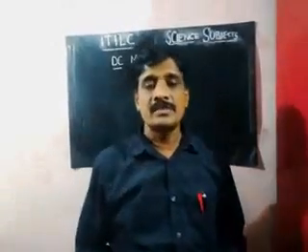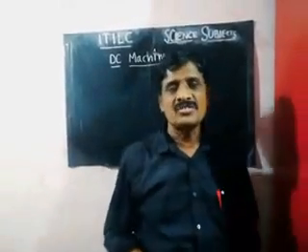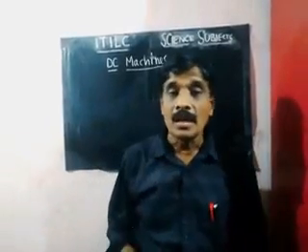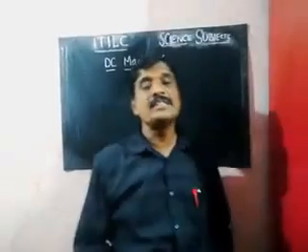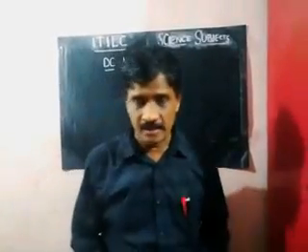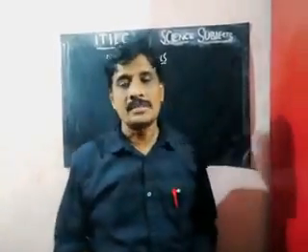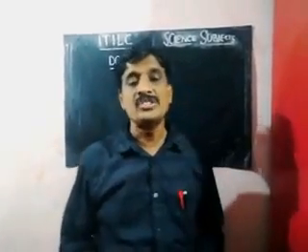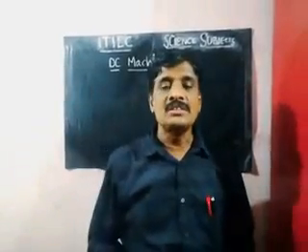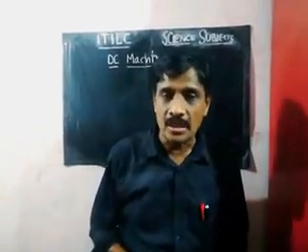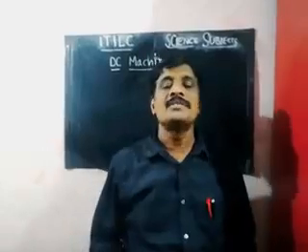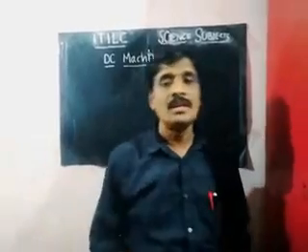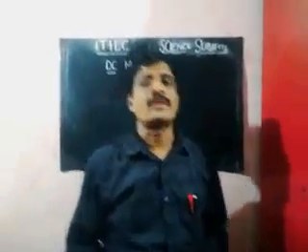And the second one is the rotor, that means the armature. The armature unit rotates inside the magnetic field. The rotor comes with the commutator. When voltage is induced in the conductors, it is taken out through the commutator with the support of the graphite brushes, that means carbon brushes. We can take out the DC power.